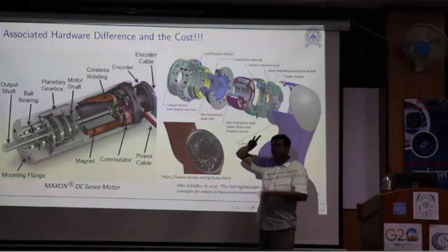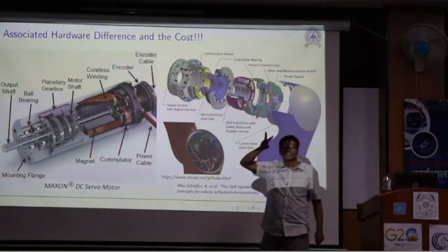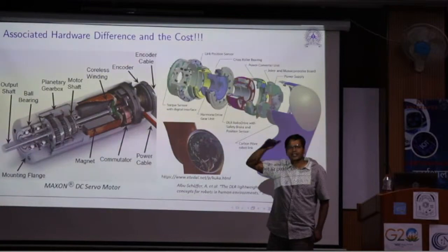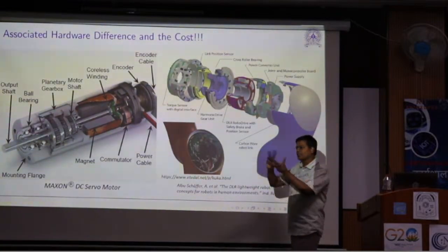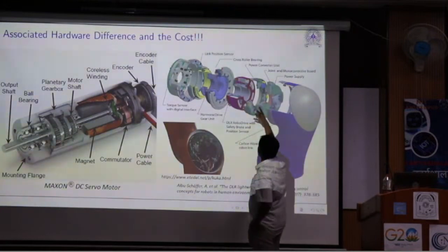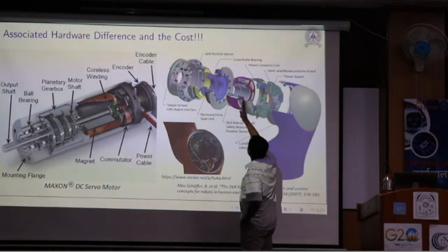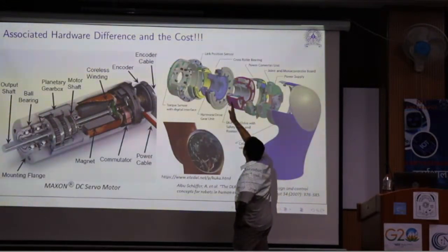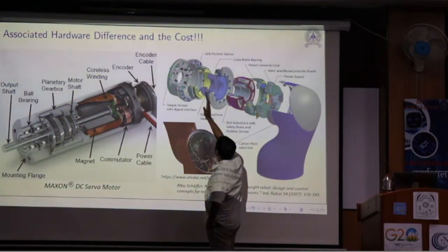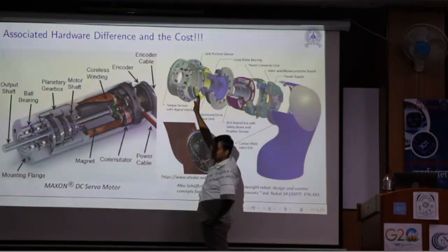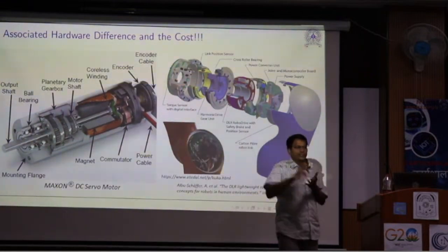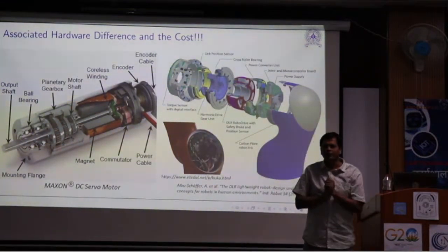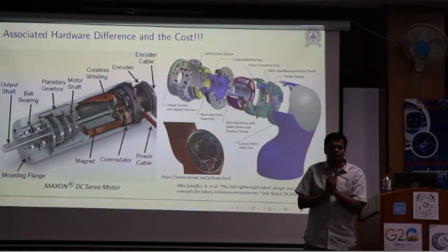Let us say it is an AC servo motor unit with 3 phases, and that can run in clockwise or counterclockwise direction. So 3 phases are there, and that whole sort of driving circuit is there. Then you have a motor, then you have bearings, and you have a link position sensor as well as a torque sensor. You don't just have a position sensor, you also have a joint torque sensor. Two parameters are now sensed.